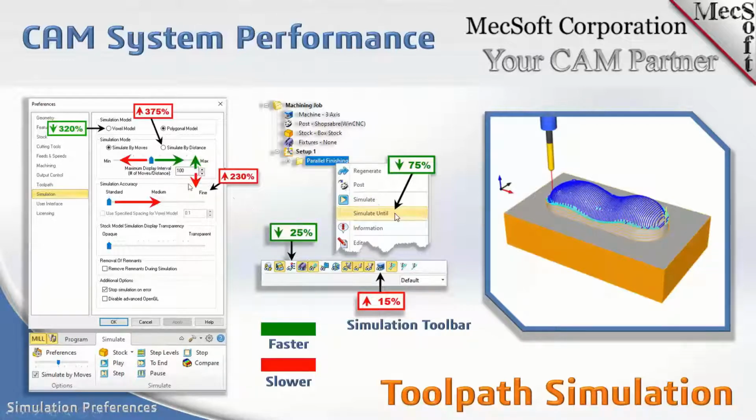You can increase this to, say, refresh every 1,000 moves, and that can really speed up the time it takes to get through a complicated model. You may see a refresh every, I'm just going to guess, 2 minutes versus one every 30 seconds. And again, that's by moves, so simulate by moves is the fastest.